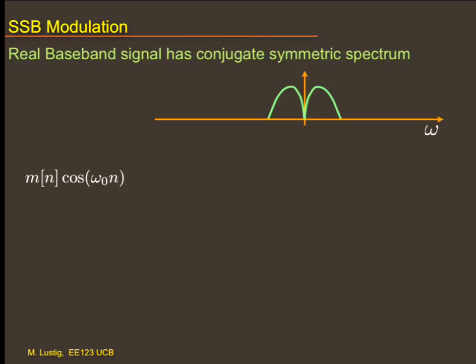Now, if I want to send or transmit this, often what people will do is modulate that baseband signal. My voice would be baseband because it's close to DC. And it's going to be modulated to a higher frequency. One of the ways to modulate is amplitude modulation. In amplitude modulation, we take the signal and multiply by some cosine at some frequency. Okay? And then that will be modulated.